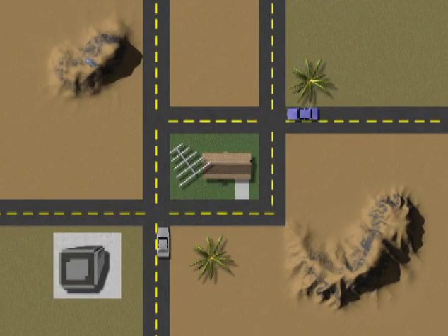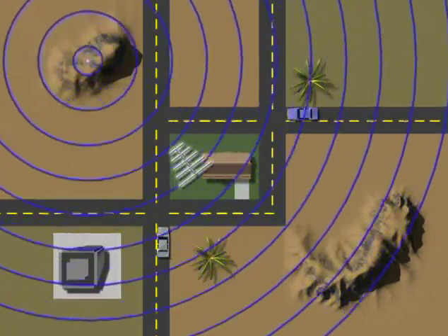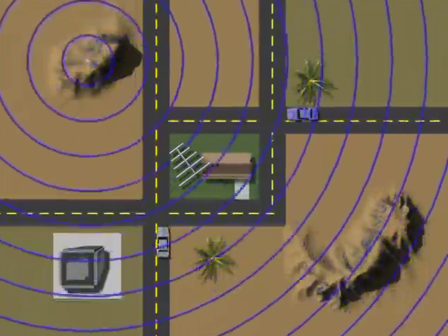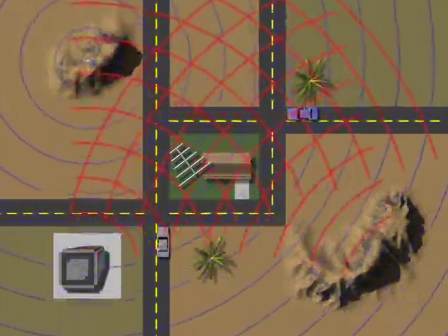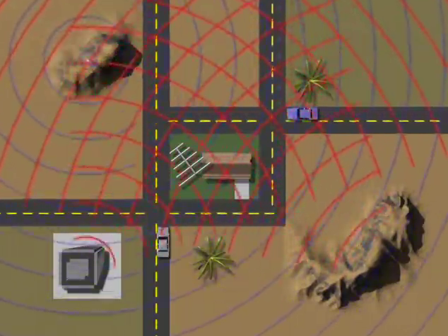One of the biggest problems you'll need to deal with when using an off-air antenna is multipath reception. The signals transmitted from a broadcast antenna travel in a direct line of sight to the receiving antenna. However, signals from a broadcast antenna can be reflected from nearby objects such as buildings or mountains and also arrive at the receiving antenna slightly delayed, like an echo, usually at a lower signal strength.